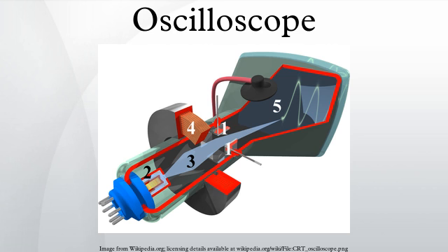In the case of repetitive, but quite complex waveforms, variable hold-off can create a stable display that cannot otherwise practically be obtained. Hold-off. Trigger hold-off defines a certain period following a trigger during which the scope will not trigger again. This makes it easier to establish a stable view of a waveform with multiple edges which would otherwise cause another trigger. Example: imagine the following repeating waveform.